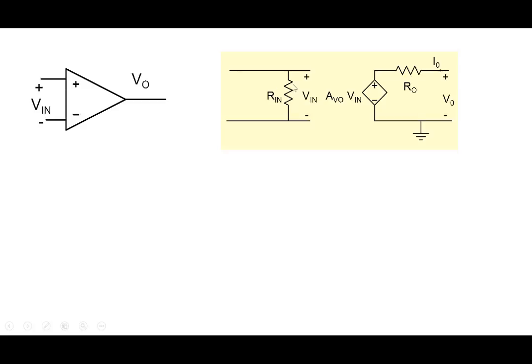It can be modeled as a resistor that you see here, Rin. And at the output side, the amplifier behaves like a resistor that you see here and a new element that you see here, denoted by this symbol. Note the plus and minus, so it's a voltage source, but it's a dependent voltage source. So we are modeling this particular amplifier. Please keep in mind we are saying modeling. The amplifier inside has resistors, transistors, and all of that. We are not right now interested.